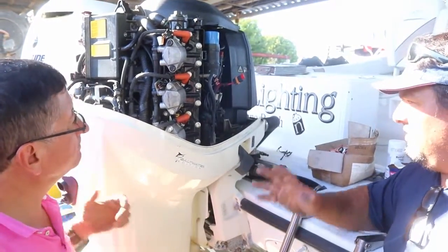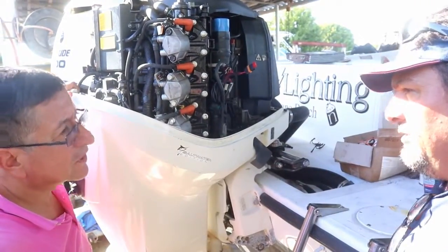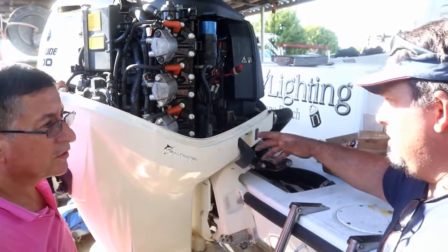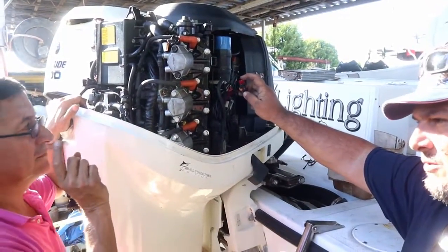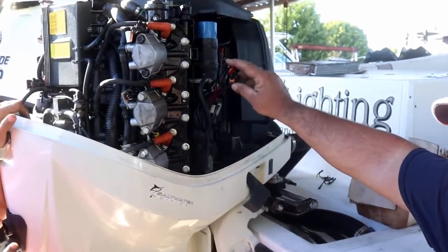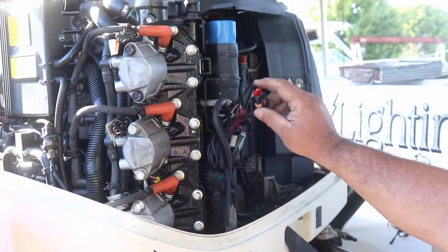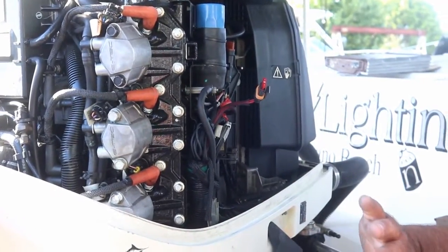Okay, so the ignition system works like this. You have the harness that goes from the motor to the console, which lights up your gauges and your ignition switch. And you have its main 10 amp breaker. That's the same thing we saw on the MerCruiser, but it's a 10 amp. It's that one. So if this breaker is broken or bad, you're not going to get any power. Trim and tilt, you're not going to get anything. It'd be almost like a dead motor.